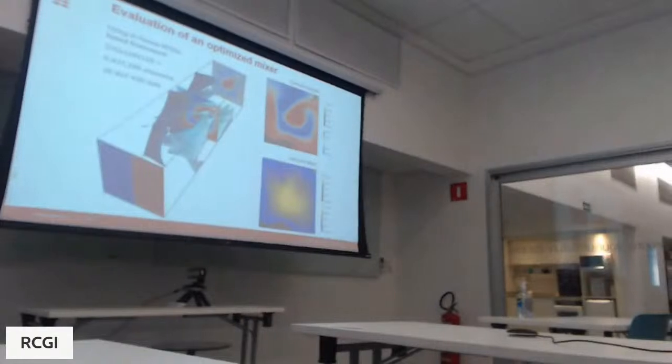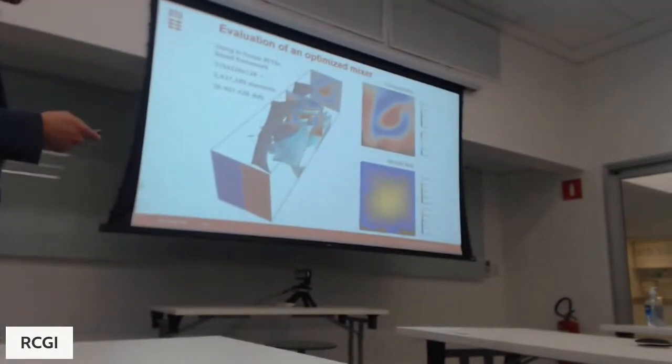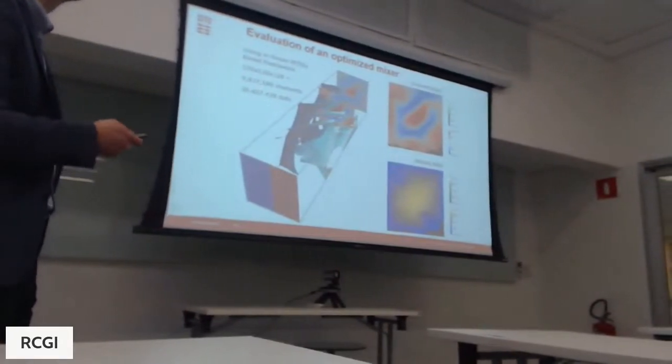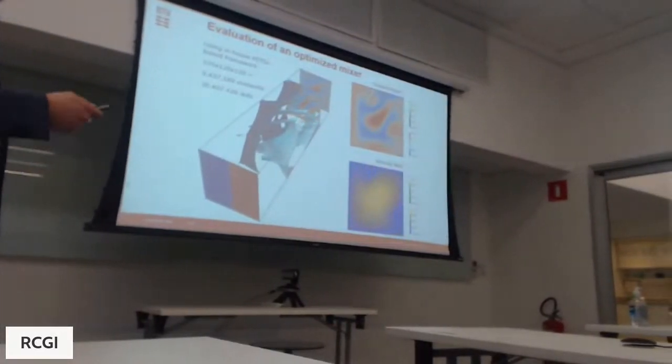You can follow the, here it says concentration. You could think of it as either a concentration of a dilute suspension, or it could also just be the temperature as I'm motivating. And you could also see that there's definitely some stretching and folding going on here in this mixer. It's on a small scale, for a low Reynolds number, even though it is a large scale resolution. Or, you know, a very viscous fluid. Of course, for turbulent flow, it might mix all by itself, and then it's not so interesting.